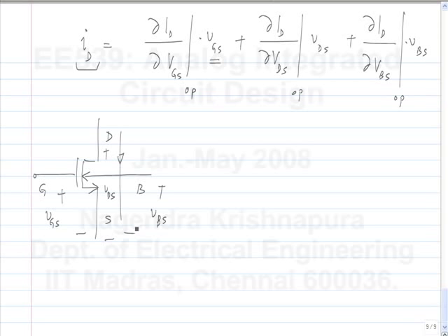Okay. So what is the small signal model? What are the circuit elements in the small signal model? Here the causes are voltages and the result is a current. So, it is a voltage controlled current source in general. Okay. So, similarly, if you had some controlling current, it would be a current controlled current source and so on. So, for each of these we have a current source.